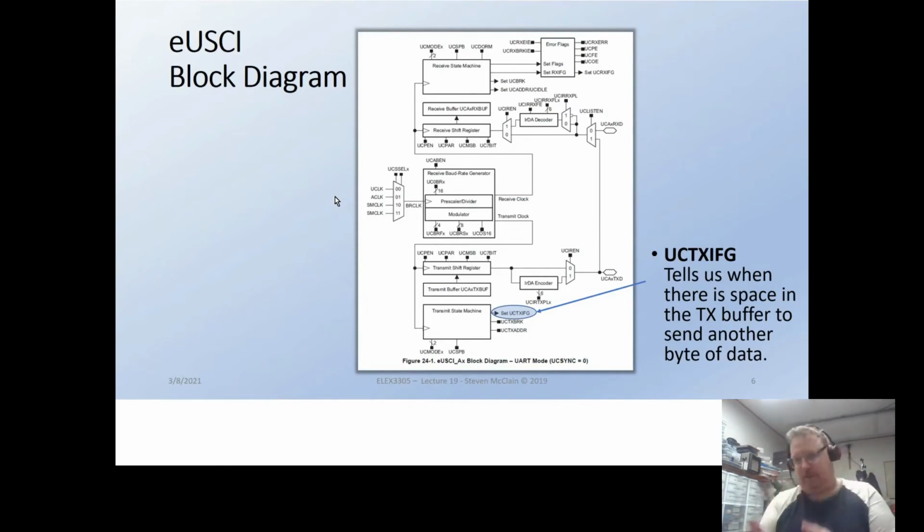But yes, you can do an interrupt with single bytes. Every single byte you get an interrupt, and you just handle it. Say, oh, I received one. Put it where I'm going to put it. Reset the interrupt flag, and it's the same thing as getting a push button.